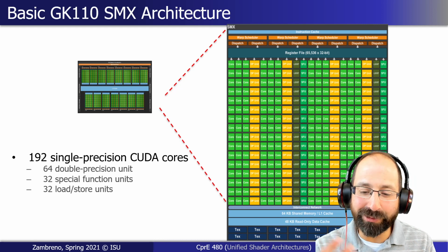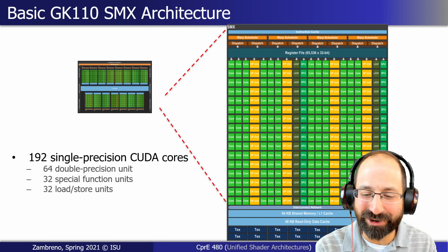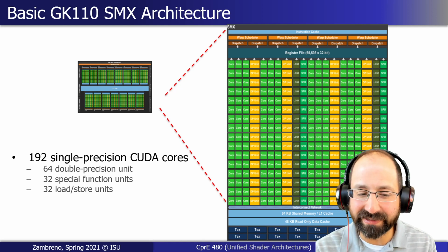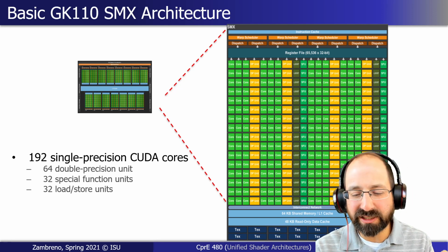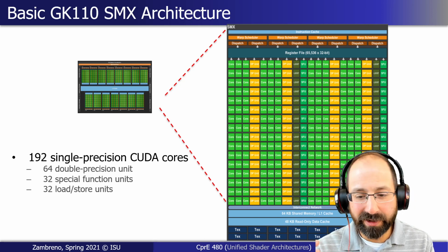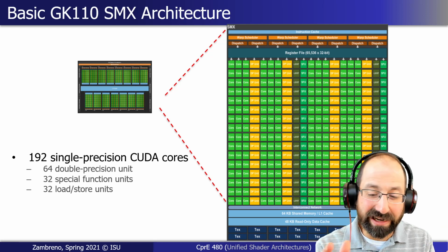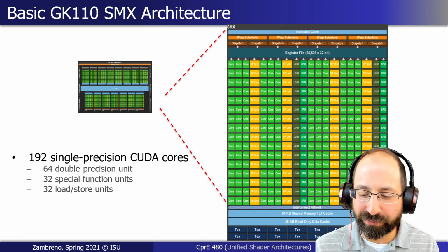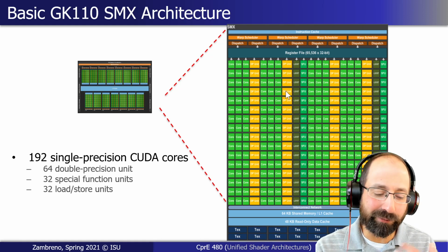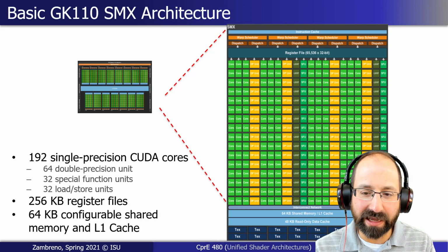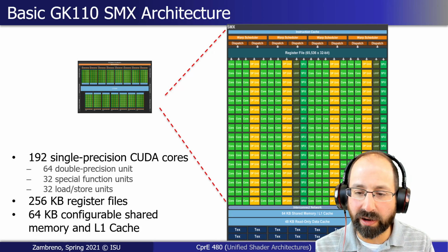Real code needs floating point hardware. So I understand why these are all floating point units here, but from a design perspective, in terms of the hours we have dedicated to this class, fixed point and using that precision, although we've seen the headaches involved along the way of underflow and overflow and truncating too early or truncating too late, it's probably still the right trade-off in terms of being able to fit even what we have so far on the chip that we're using this semester. No pressure on the group to get the next device working here as well.